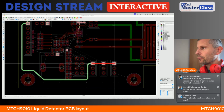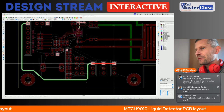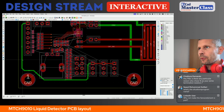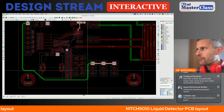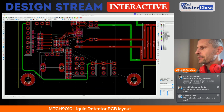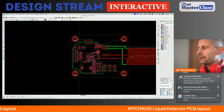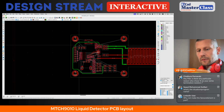For the interconnection of these three jumpers, I will use the top layer, because at the end I will need the copper pour of the reference plane on the bottom layer. And if I use the bottom layer for interconnection of the 3.3 volt, I would make the possible path for the ground thinner. So yeah.